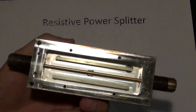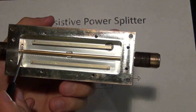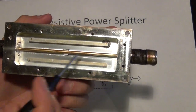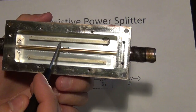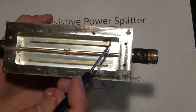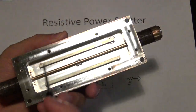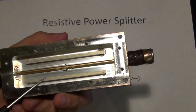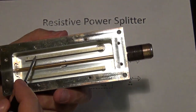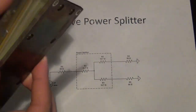So here it is. It is a little bit weird because the input and the output are directly connected to each other through this line, through this copper wire that's running in the center. This is the other port, and this is the other port, the minus 40 and the minus 50. And this distance between them is enough for minus 40 or minus 50 dB of the power to couple to this line. So this is all they've built. All they've built is they've calculated this distance, they've modeled the electromagnetic fields around this inside of this unit, and they figured out that at this distance and at this type of orientation, they're going to get minus 40 and minus 50 dB of coupling, and that's it. That's all they need to do in order to get a coupler like this.